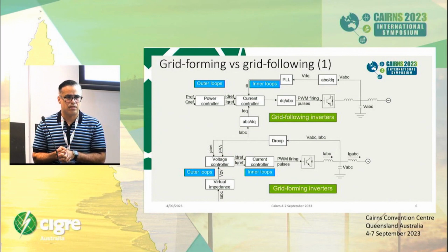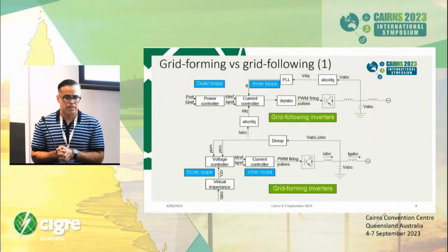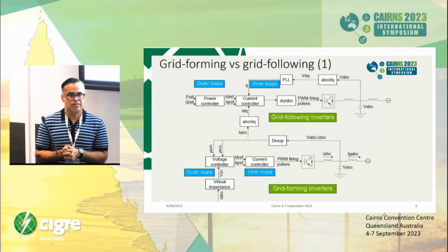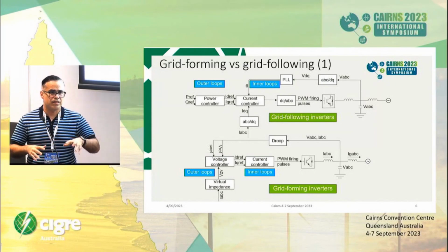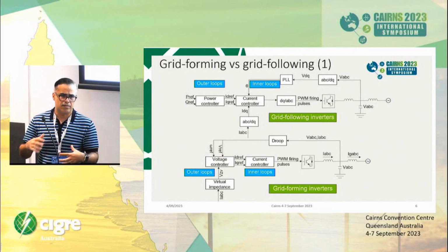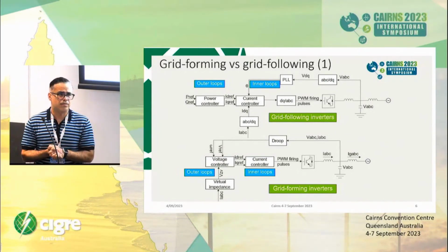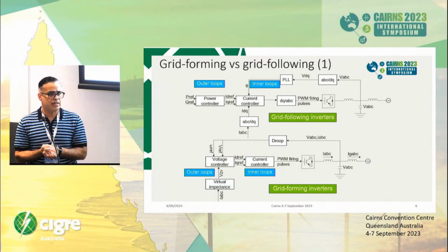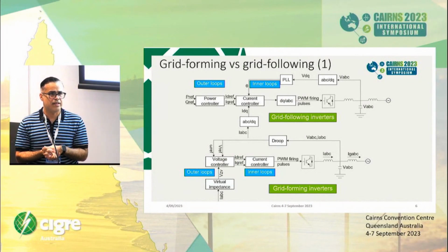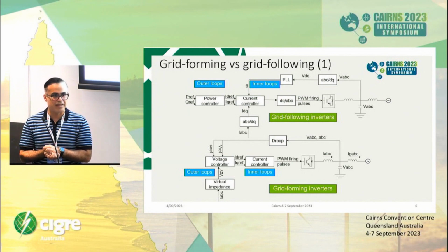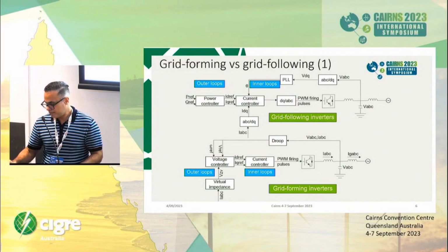We have had discussion on the impact of, for example, additional fault current, and this is an ongoing work that has been done outside this technical brochure. But the key answer or conclusion is that a lot of the things that we are using grid forming synonymously with are not necessarily to do with grid forming, but more to do with the storage capability that grid forming devices are bringing in. And perhaps one of the key conclusions is that we cannot restore a power system even with 100% grid forming if none of them is based on storage.